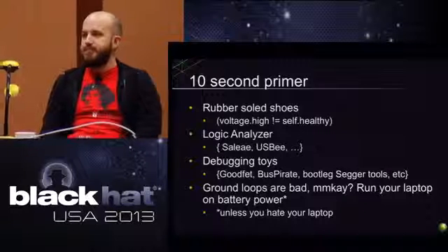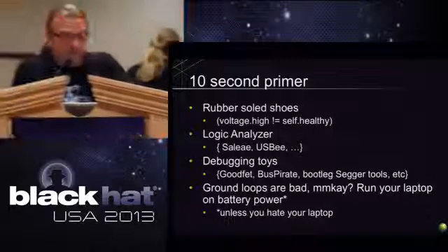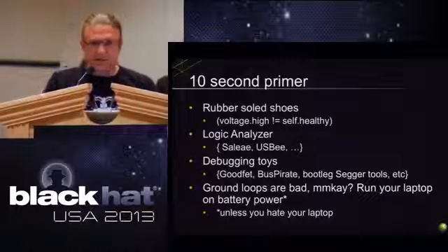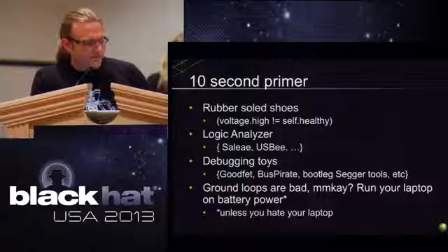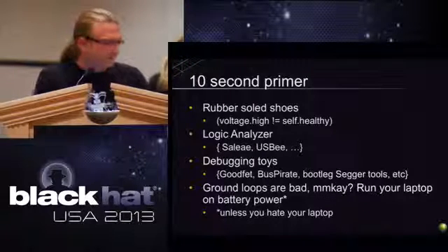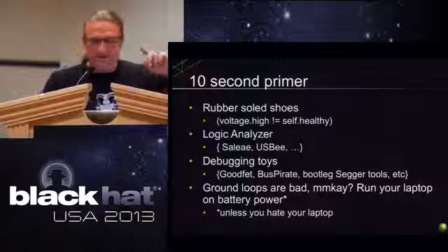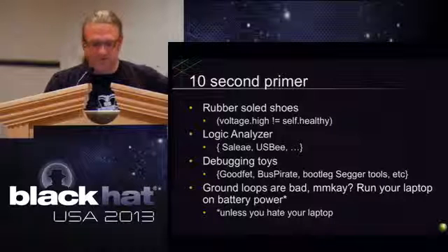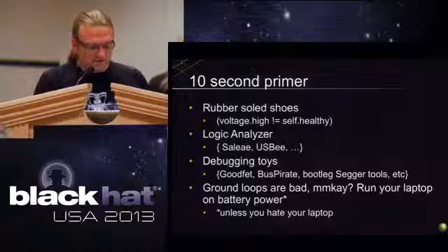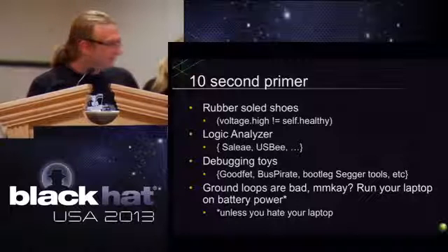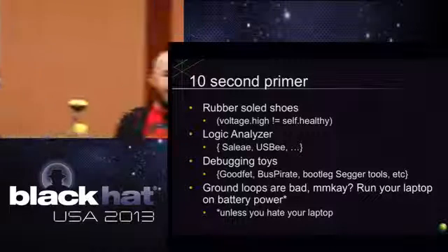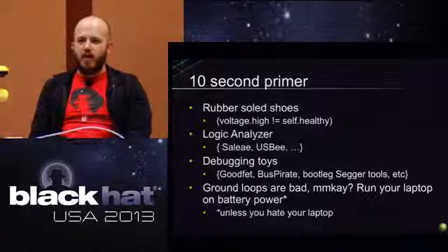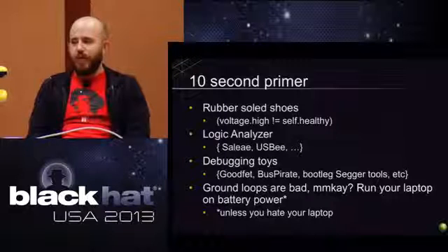Yeah. And the last pro tip that we've got before we really get into the meat is if you're working on high voltage, or typically almost any embedded system, if you are powering that device and you're running ground on the same plane that you're running your device, like if we're running 110, your laptop doesn't like that and you end up doing things like frying your USB ports. If PCBs were designed correctly, that would never be a problem. But when you get into debugging interfaces and stuff like that, there's a couple of them out there that are known for letting you electrocute yourself or frying your laptop.